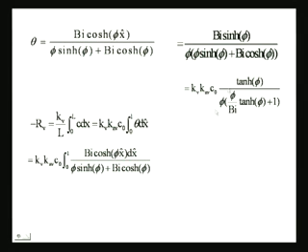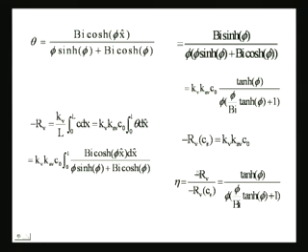Now, why do I do that? Because I need to evaluate the eta, the effectiveness factor. So, I just need to evaluate that. So, my RV, the average volumetric average, is given by kV over L times integral of this from 0 to 1, okay, which is the integral of this. It is a little complicated integral, and then eta comes out to be tan hyperbolic phi over Biot number tan hyperbolic phi plus 1. This is what it comes out to be. This is because RVCS is this number. So, this gets cancelled with this over here, and this is what remains.